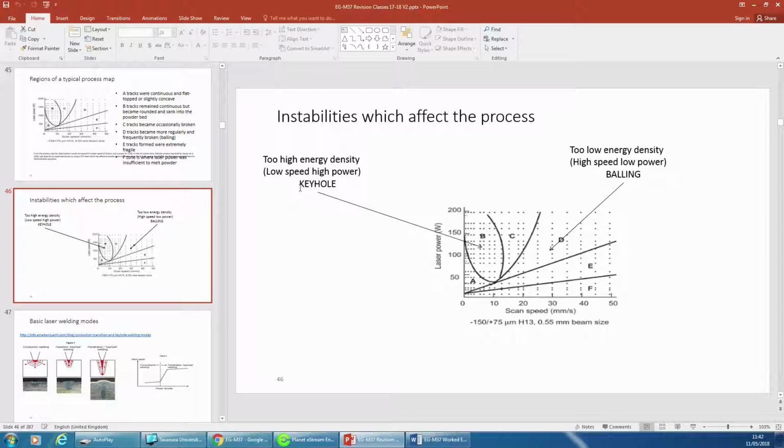In our case, though, it's not necessarily a good thing, because you are going through into the layer below, and you're introducing porosity on quite small distances. If you introduce porosity through it and go into the next layer, then you're getting more porosity in the part. So in powder bed, it's something to be avoided.